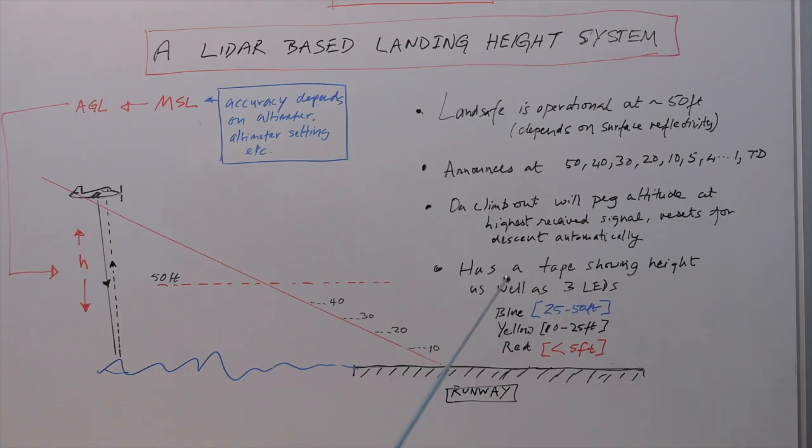And in the examples I will show landing an aircraft, and that altitude will change where it starts to work and where it stops working. So there are things you have to worry about. But in general, below 50 feet or so, it will start typically engaging, and the information that this instrument will start displaying will be valid at some point. So that's the good thing about it. It will actually reset itself on landing.